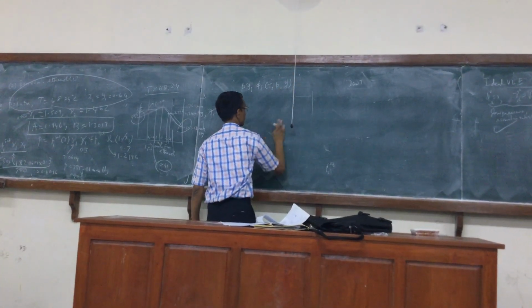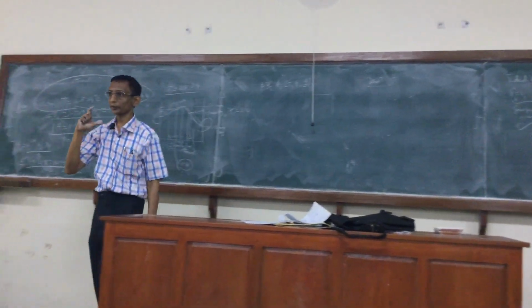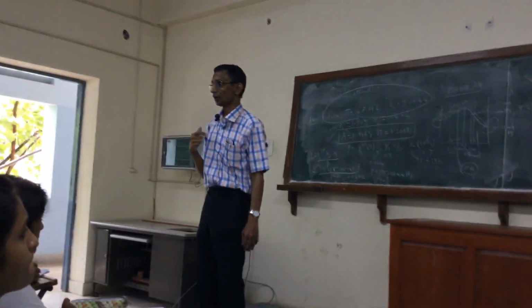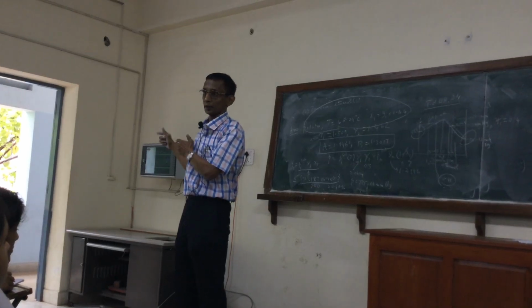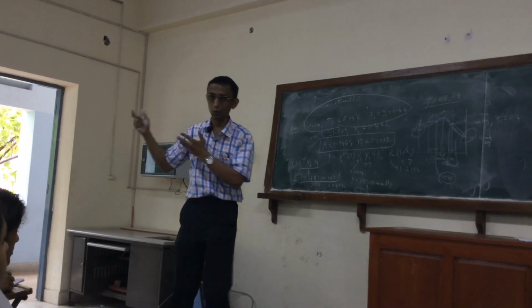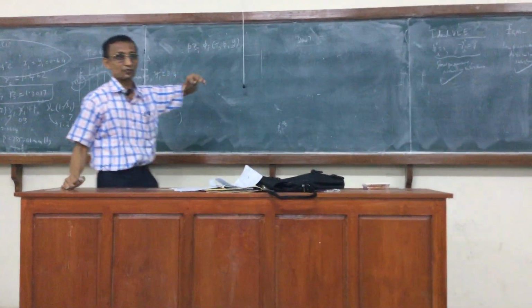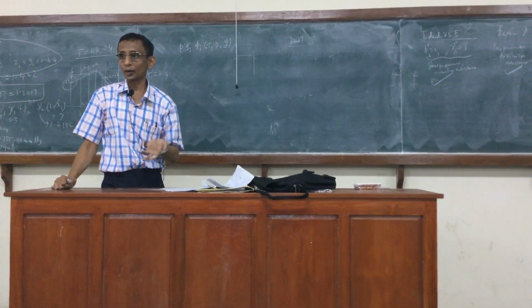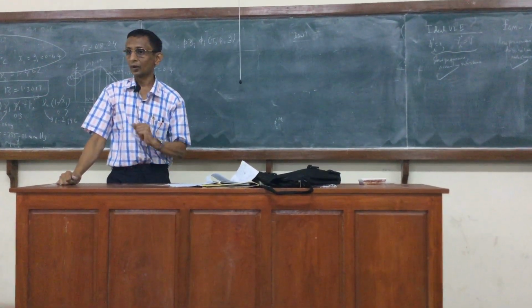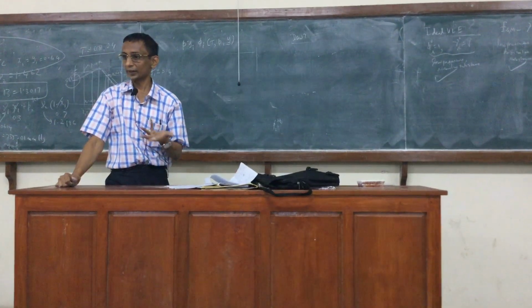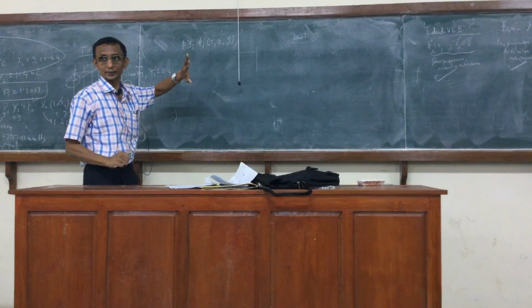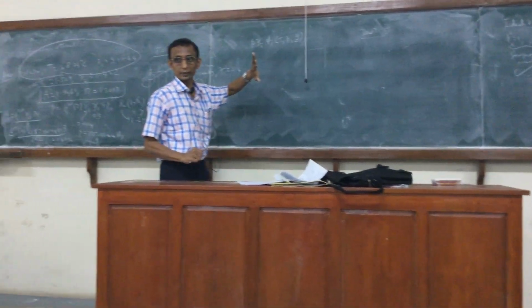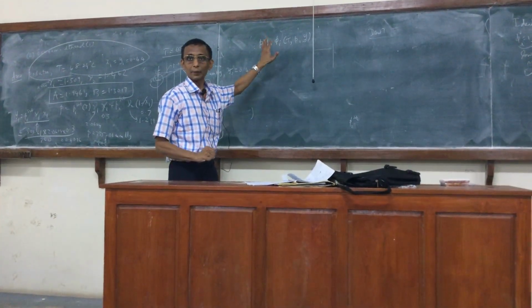I just want to point out some elements of the structure of the algorithm which should help you construct the others, because there are so many other specifications, both the phi gamma and the phi. You cannot be memorizing all these, so you should be able to sit down and work out the algorithm yourself, but that's quite easy to do. You should just look at the way we constructed the algorithm for the phi gamma bubble pressure.